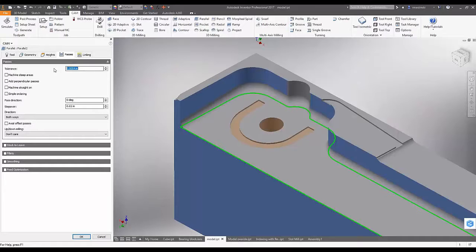So if you can picture a circular part with a stop sign shaped circular containment boundary with a stop sign shaped part in the middle of it. You've got these triangular shapes where the toolpath could kind of sneak in based on if there's a toolpath in the middle of that triangle. It's kind of hard to describe without a picture, but I most importantly wanted to make people aware of that, so you don't change a step over, repost, forget to take a look at the toolpath, and then possibly end up with a problem.